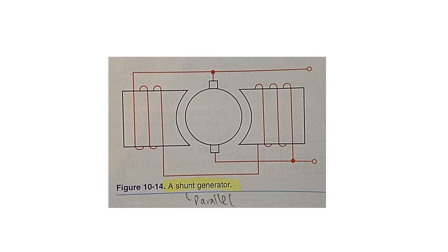The total current generated must, of course, be the sum of the field excitation current and the current delivered to the load. Thus, the output current can be thought of as varying according to the applied load. The field flux does not vary to a great extent. Therefore, the terminal voltage remains constant under varying load conditions. This type of generator is considered a constant voltage machine.